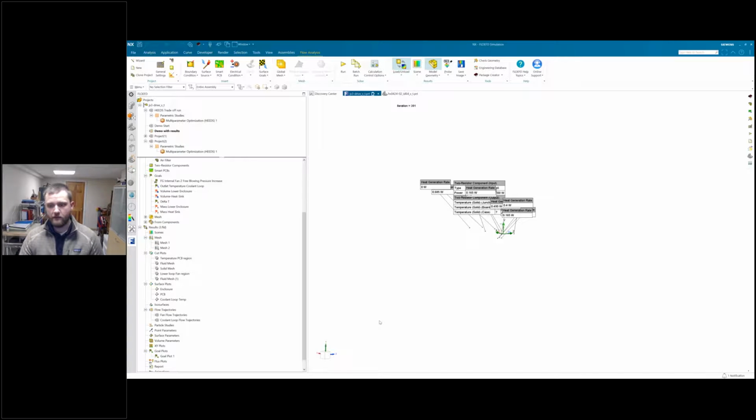So now we have a very detailed model of this IC that we can import directly into our CAD and into FlowEFD and get a very detailed analysis of this. If you can see, I'll just kind of hide the encapsulant here or make it transparent, where you can see your individual conductors. You can change the material.